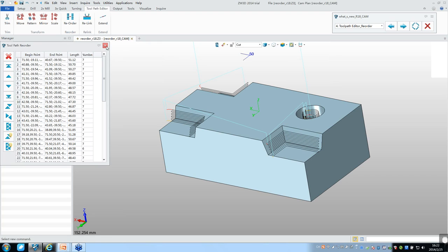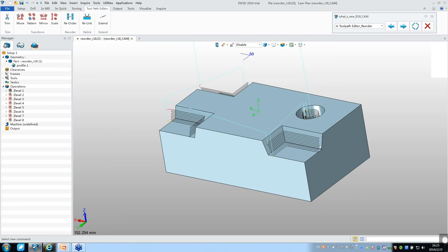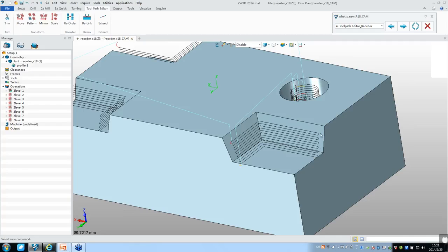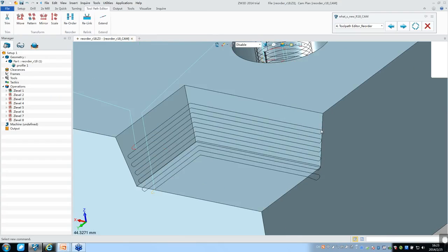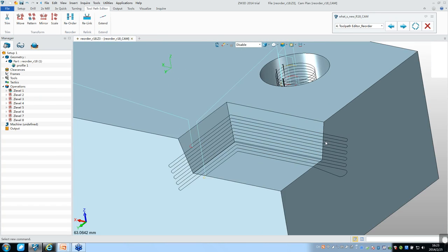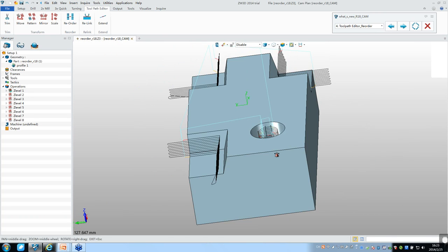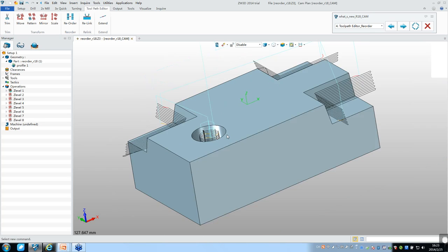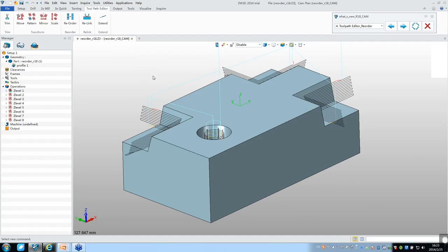And sometimes maybe you are not satisfied with the Toolpath because it's too short to cut all the face of it. So let's use this one. First highlight, you can extend all of them. Now, in order to get a full machining, again give a big value, use this. Now you get it. This is something about the new Toolpath editors: relink, reorder and extend.